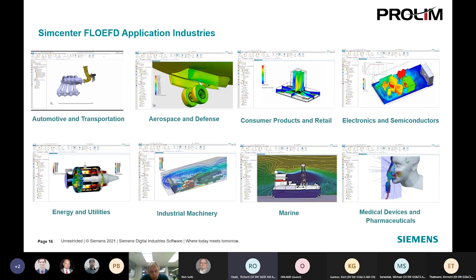Recently we've had a big request for air tracking within the built environment. Okay, so where does the supply air come from? How is it extracted? And where do the contaminants go? That's been a big focus area for us over the past 15 months or so with the pandemic, and making sure that clean rooms and air handling devices are positioned and operating correctly. And what happens if they were to fail?